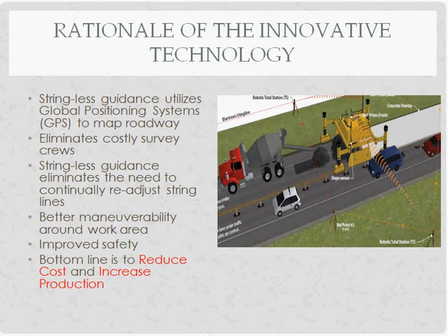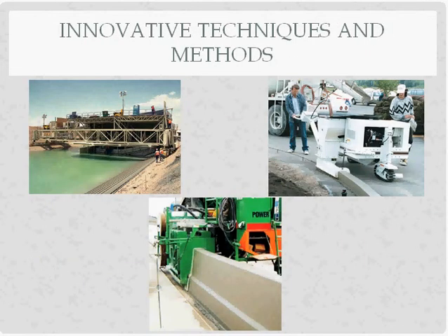One of the other techniques is the automatic dowel bar inserter. There's no longer a need to pre-position the dowels. We can do away with the costly labor of pre-positioning dowels, and the machine will automatically place the dowels for the construction joints. Here's a look at some of the new applications for slipform pavers.